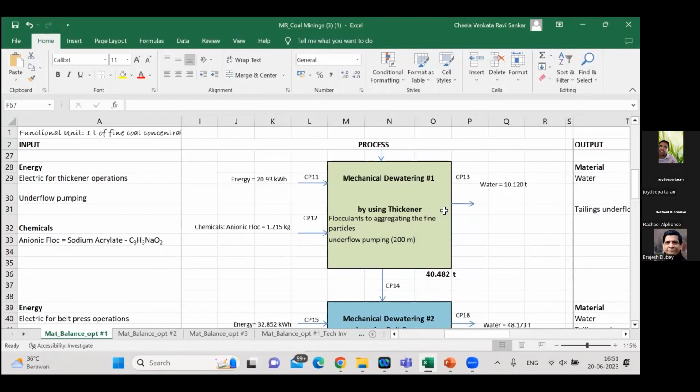Suppose, a very simple example: when you start watching the road transport sector, the transportation people will do a survey. So how many cars are passing from morning till evening? This will be a transport vehicle survey. The people will be sitting on that particular road at a given junction, from 10 o'clock in the morning to 5 in the evening. If they are doing 10 to 11, how many vehicles have passed on that particular road?